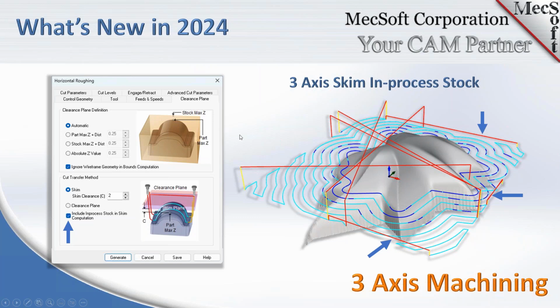Oh, another note, actually: in previous releases, we were looking at only the part geometry when we computed the skim clearance. So what Don is saying is absolutely correct, in that the skim clearance moves will reduce your moves all the way up to the retract plane and thereby enable faster machining.